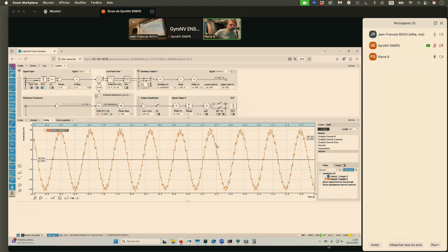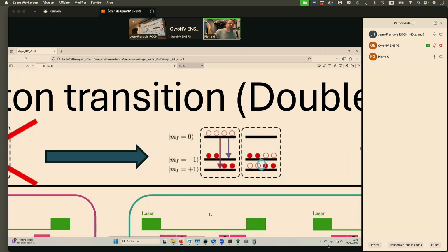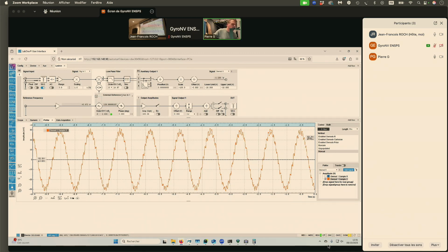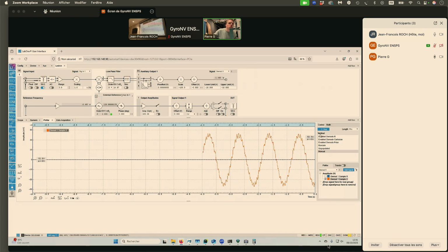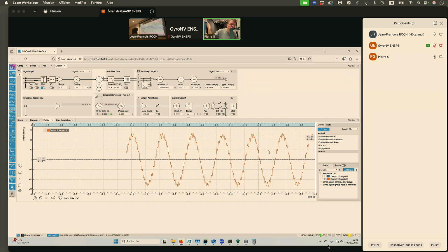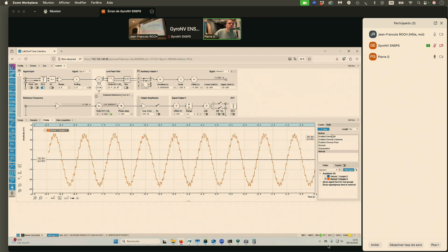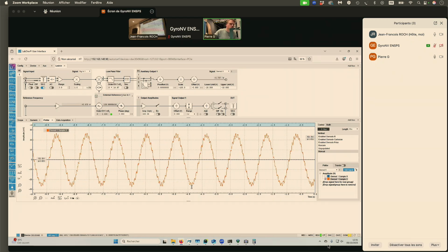Now, the faster oscillation is a 5 megahertz oscillation, and it's a remainder, a sign that the setup is not correctly set, because this should disappear, okay? It's the remainder of those higher frequency transitions. So for us, we need to get rid of it, but I don't have time to do the settings properly. The important oscillation for us is the low frequency one, and that's 300 kilohertz. Once again, you cannot rely on the time scale.